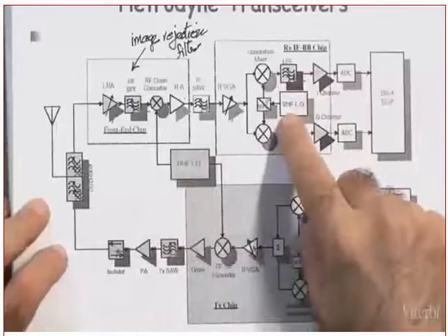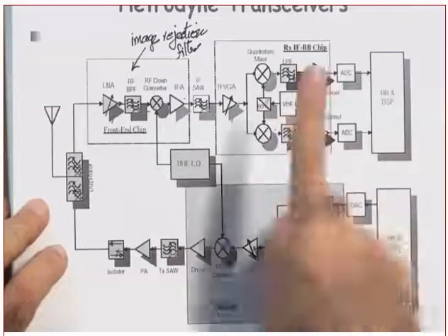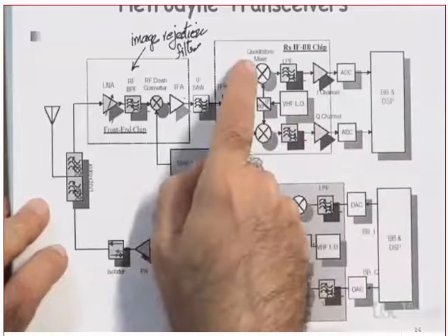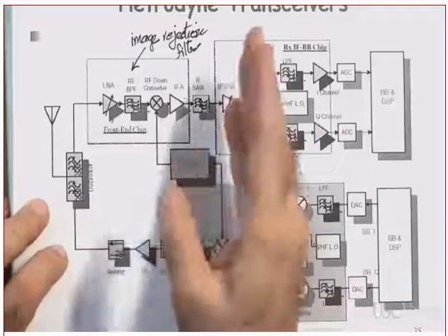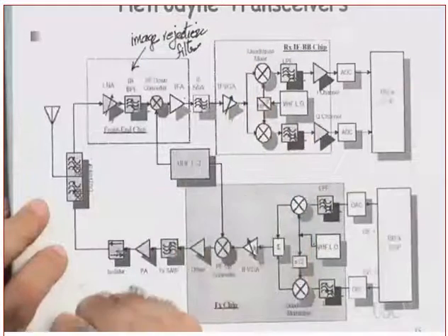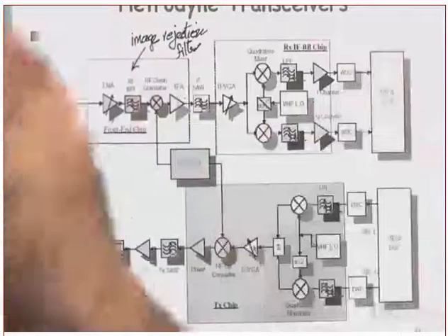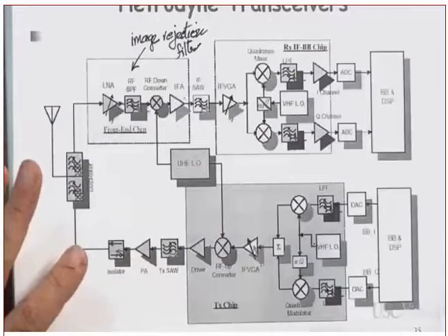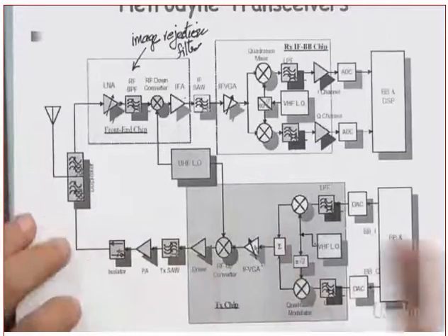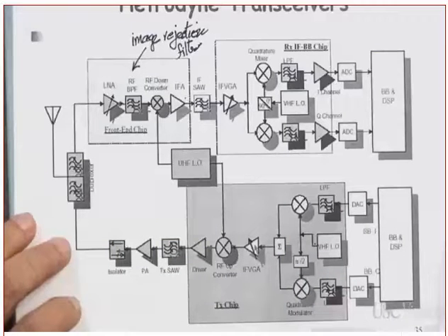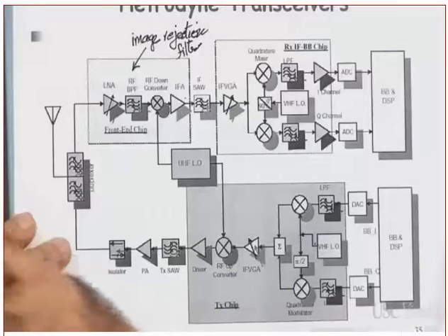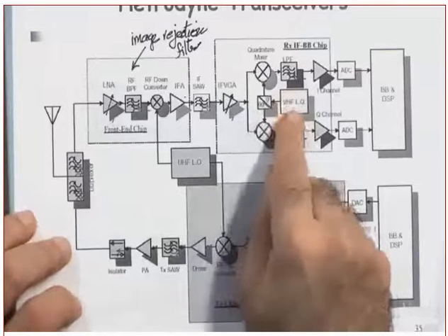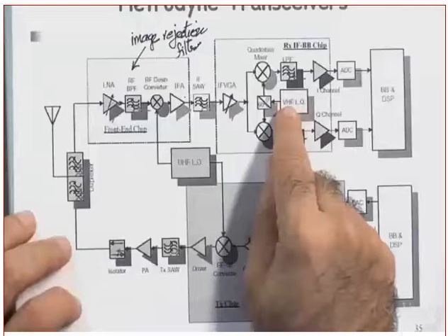What am I using here? Is that another local oscillator? Yeah. By the way, am I doing the IQ at high frequency or at low frequency? Low frequency. The performance of IQ in terms of symmetry, the drifting offset, is much better at baseband, at low frequencies, rather than high frequencies. Clear? We have a VHF, the very high frequency local oscillator.